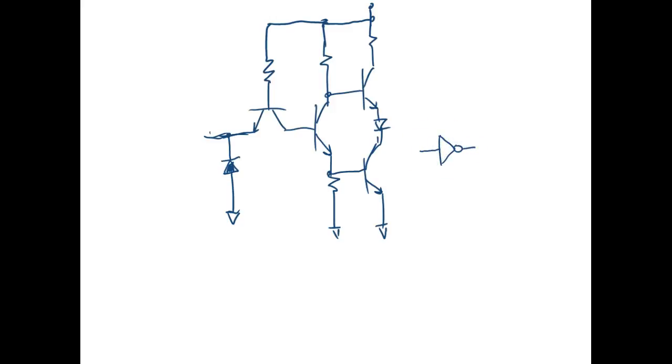So what we're doing is solid state. We can do this with relays, but relays are electromechanical, right? And they take a lot of current. The output comes right here, I'm sorry. So there's our output. If this transistor right here goes bad, we don't troubleshoot it as a transistor, we troubleshoot it as this whole gate right here. So if it was bad, we've got one of two options.